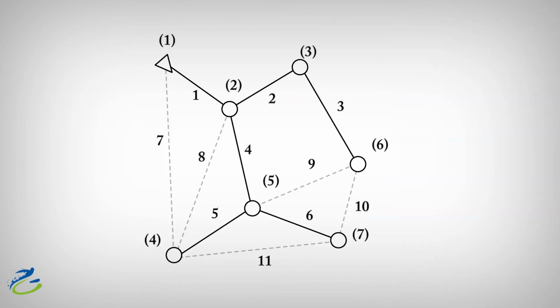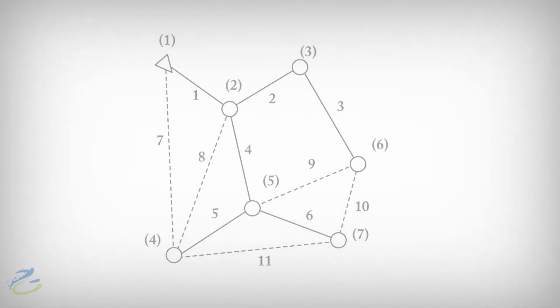This is an example of a water supply network with one source. The tree network that supplies water to nodes 2, 3, 4, 5, 6, and 7 is shown as continuous lines, and the redundant links are shown as dotted lines. When we increase the dotted lines, we increase the reliability. We can also count the basic closed loops 1, 2, 3, 4, and 5, which is the same number as the redundant links, as we will see in the topology section.